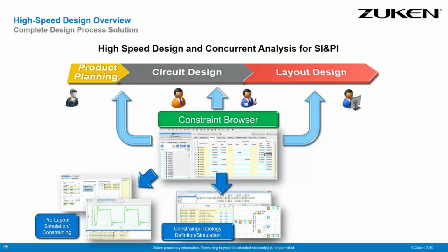These topology templates can be amended with rules, with a routing layer, with a target impedance, with length definitions between two pin pairs, with any kind of termination rules. And then by assigning such a topology template, which can be extracted from the routing as well, so you can reuse existing IP, to a net or to groups of nets, these nets automatically will inherit all these rules. So this allows a smart and fast constraining by hierarchies.